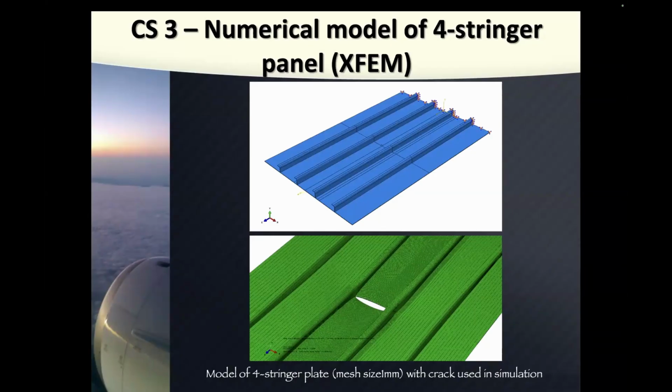So the crack grew from the initial 14 millimeters and then spread along this horizontal axis, then came to the first 2 stringers, broke them, then came to another 2 stringers, broke them, and finally complete failure of the plate with stringers.